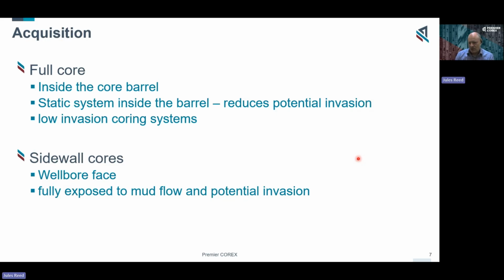However, for the sidewall cores, one of the potential issues with sidewall cores is that they are obtained from the wellbore face. And the wellbore face is being continually exposed to a moving mud system, or potentially moving mud system. Yes, a mud cake will build, but the shear forces of the mud system itself could begin to remove portions of that mud cake. You then have higher potential for invasion into the sidewall cores.